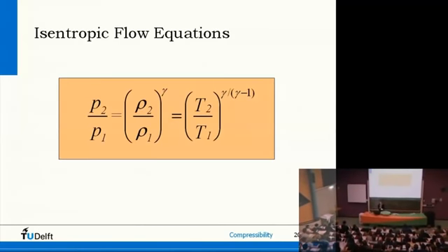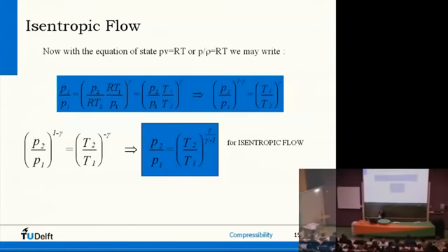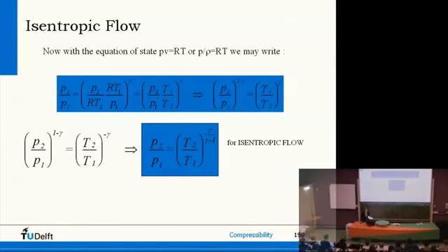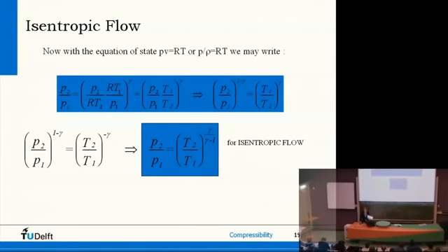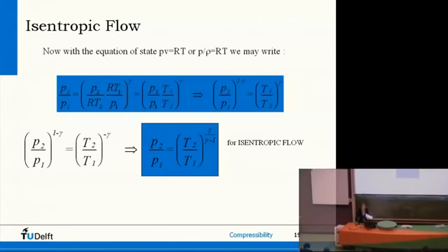So what do you need to remember? The isentropic flow relations I just derived. I got lots of questions on this last step, from here to here. In case you were not here to ask me and you don't really understand what is happening, you can see this as a pressure ratio, P2 over P1 to the power something. Suppose it's squared, suppose this is 2. What do you do to get to just P2 over P1? You take the square root. Taking a square root is doing it to the power 1 over 2, so to the power 1 over. That's what I actually do here.